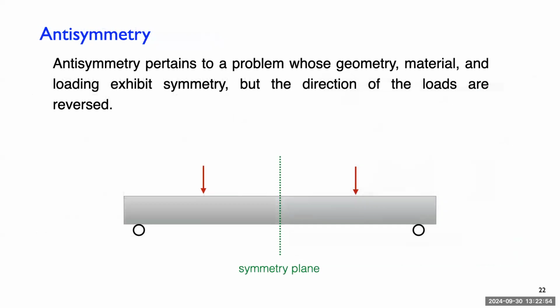And the last one, which you may have seen in Abaqus already, when you go to select boundary conditions, you'll see X sym, Y sym, Z sym, but there's also anti-symmetry. This one's a little bit stranger, but imagine we set up a problem like this. This is a four-point bend. I have some supports here, I apply a load there and there, my material I assume is isotropic, and I have a bilateral symmetry plane here. So we can use just a classic symmetry plane here.